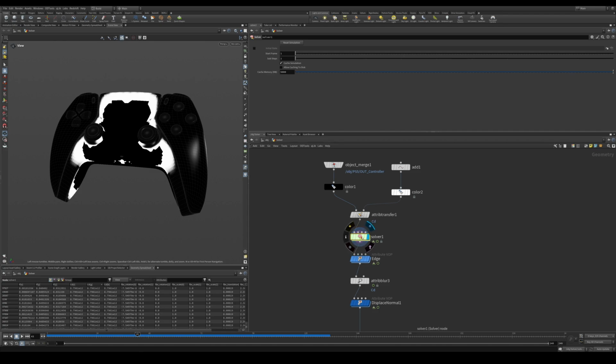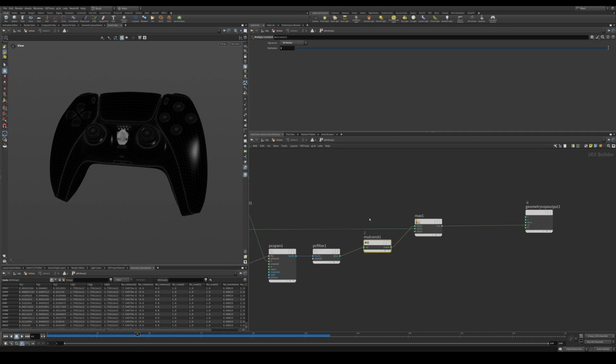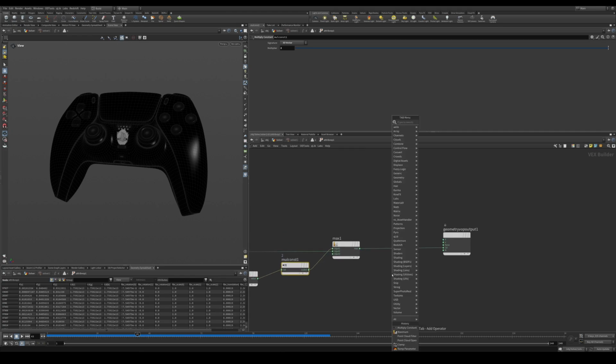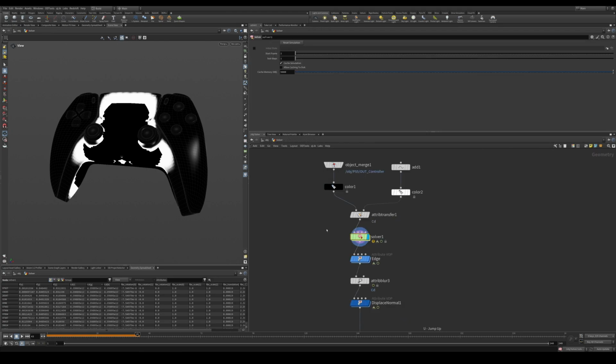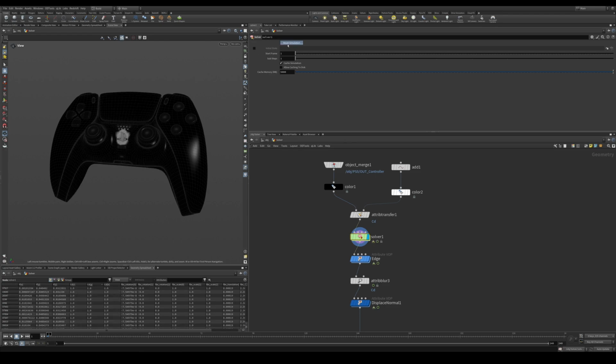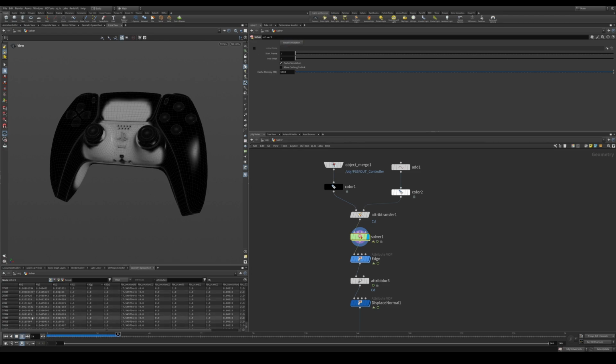So in order to fix that issue, we will go into the end of our setup here, and we'll create a clamp. And then this brings the numbers back down to a reasonable level. So it's from 0 to 1. Without it, it goes into way high values that we don't want. So just put the clamp in there. And if we go back one more time, let's rewind it, reset simulation. Now we can see it spread around.